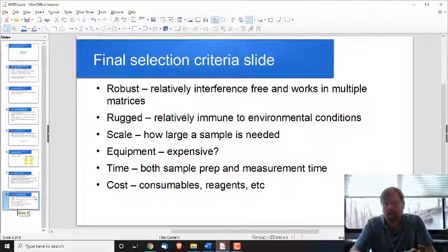So depending on what you're measuring, you might need 6 hours for the sample to go through the gas chromatograph, and then you can get another sample through, and so they can still be very time consuming. Sometimes you can adjust that time as a trade-off with selectivity or sensitivity or detection limits, depending on what you're trying to do. There's some trade-offs there around time.